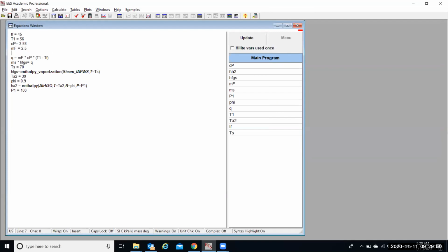We have a case of M_D equal to 1 kilogram per second, and we need to know the vapor temperature at state number 1. So HFG1. I need now the enthalpy of evaporation, but at another condition. I can follow Options, Properties, Thermodynamics, or simply I can copy this, Control C, Control V, and change this to be T1.